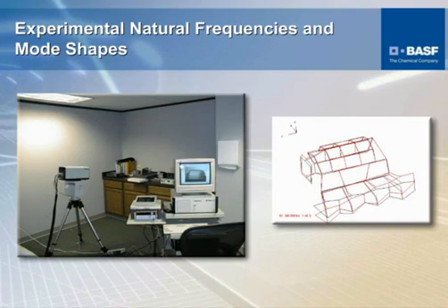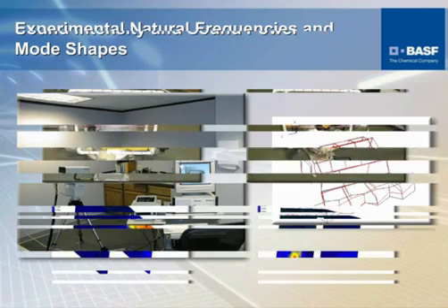Laser vibrometry, where we can actually extract the actual movement at the surface based on the velocity Doppler shift. There is a laser that gets pointed on the structure and then gets reflected back, and it's read by the machine. We do that at different points on the structure that are basically represented by a grid, and then we can get the information readily on the screen.